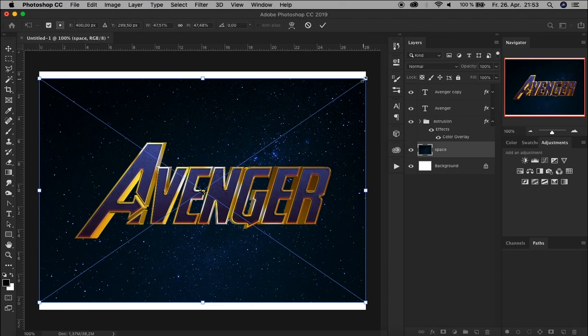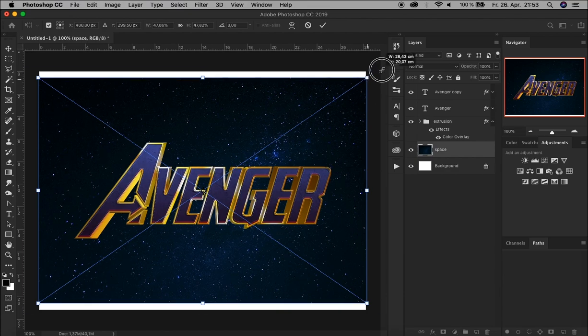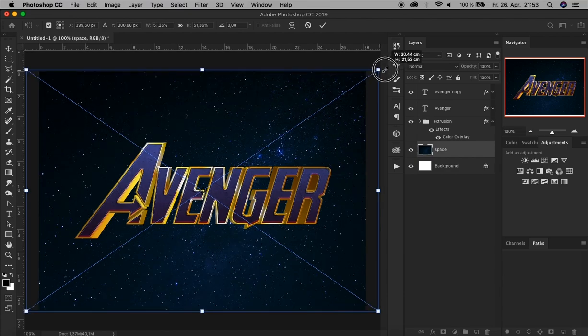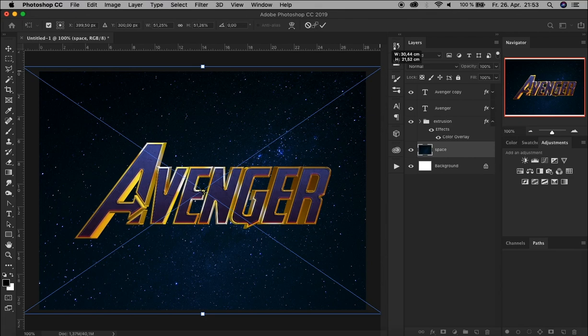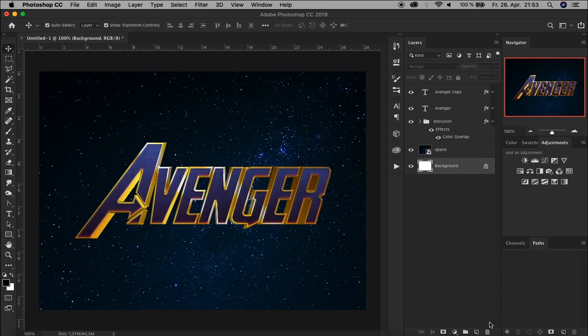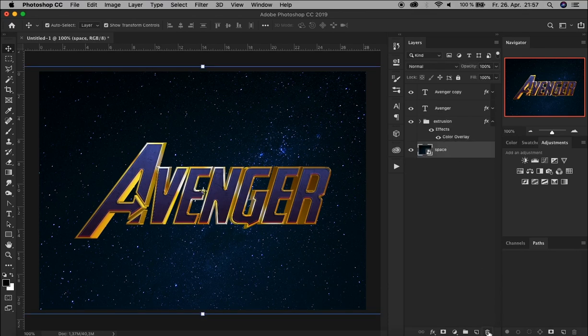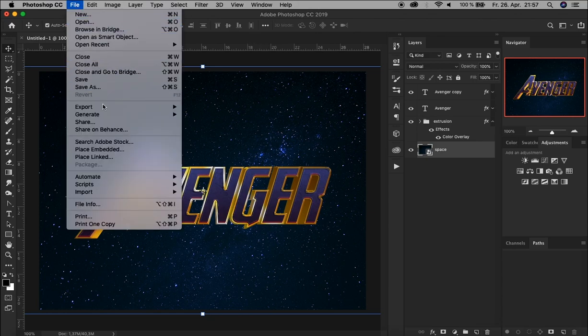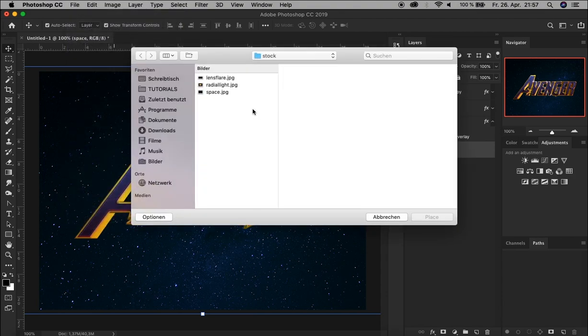Right, let's hold Alt and resize this so that it fills the entire background. All right, there you go, and click OK. And we don't need this background layer anymore. Let's click here and delete it. Right. All right, and now let's add another image on it. Go again to File and Place Embedded.